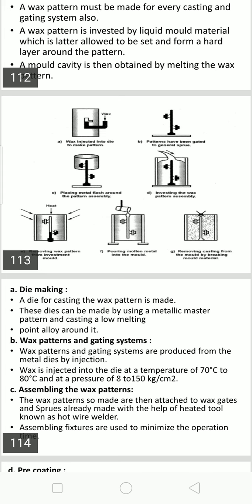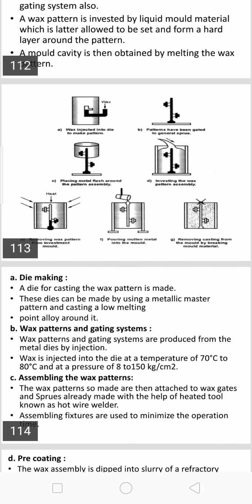The thickness of the primary coating is in the range of 1 to 1.5 mm. The assembly is then taken out and sprinkled with coarse grained silica, about 40 to 50 mesh, and allowed to dry in air for 2 hours. The coarse silica and the fine silica help to produce a better bonding between the primary coating and the investment backing.